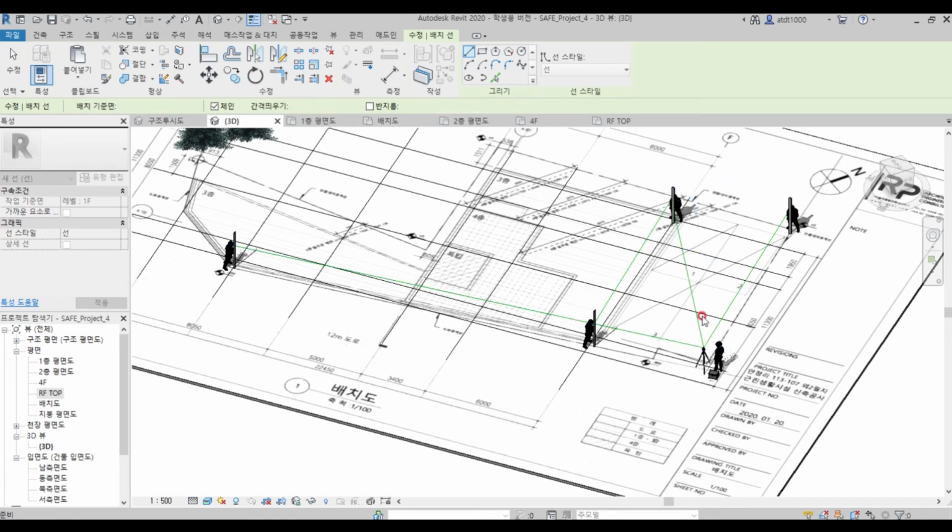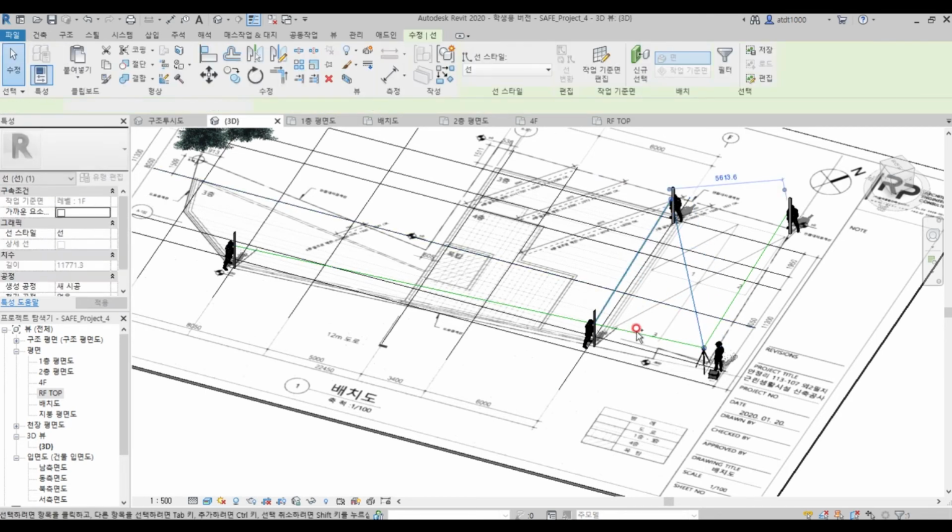So 2 directions of the boundary are shown, and a reference point of the building and the intersection of the grid and boundary would also appear. This diagonal distance can be calculated by using the Pythagorean theorem. So the coordinate of the first intersection is calculated.